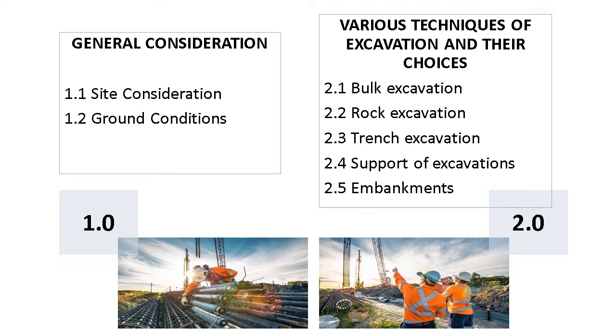Excavated material required for backfill or grading fill is stockpiled on the site for subsequent use. Unneeded material is removed from the site for appropriate disposal. There are various techniques of excavation which are bulk excavation, rock excavation, trench excavation, support of excavation, and embankments.